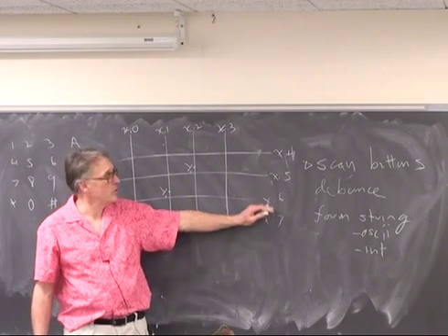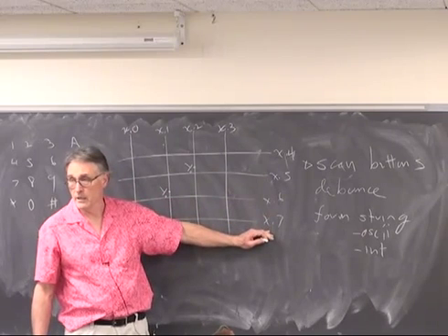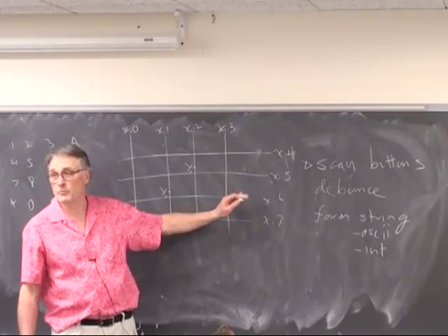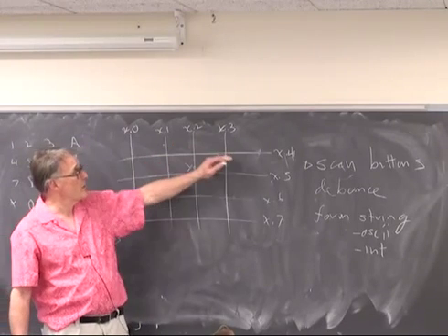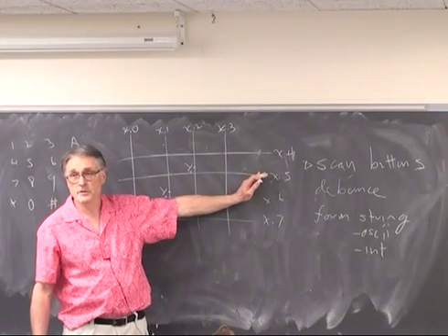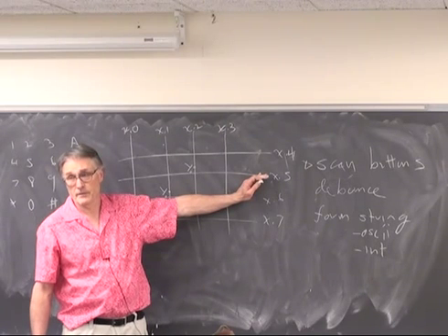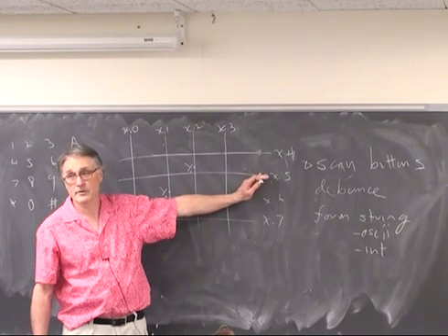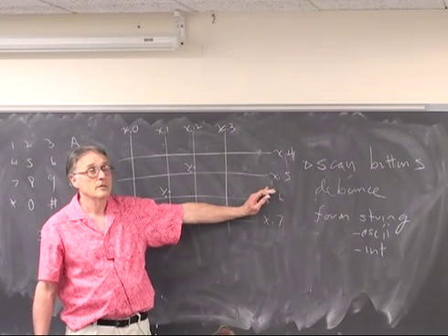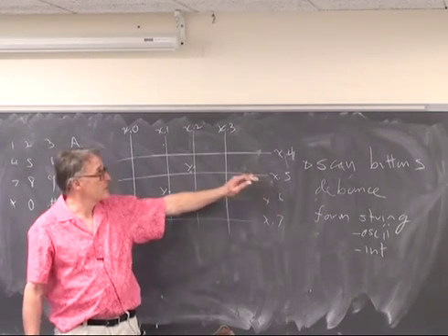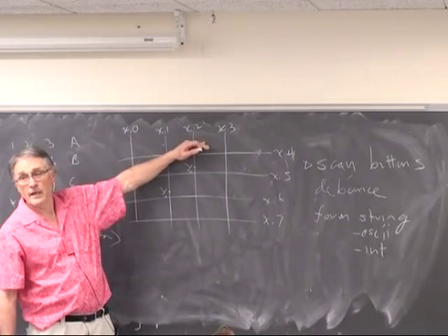So if the button is not pushed, the inputs are going to be high. If a button is pushed, it will be low on the line. Alright, so we're going to set these low, read these with the pull-ups turned on. One machine cycle later, we're going to set these to outputs low, set these to inputs high, and read it again.